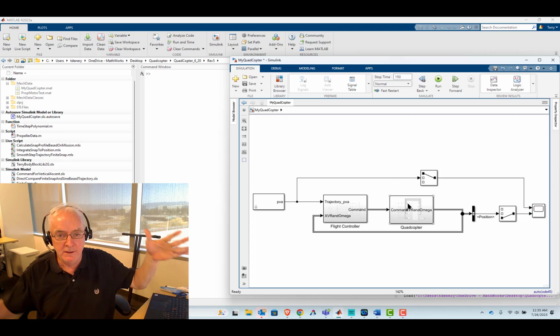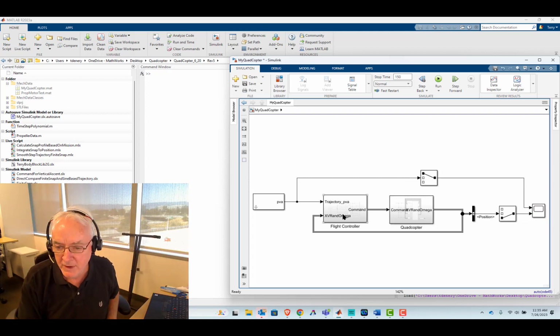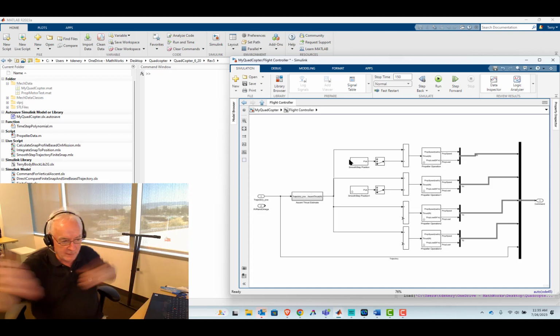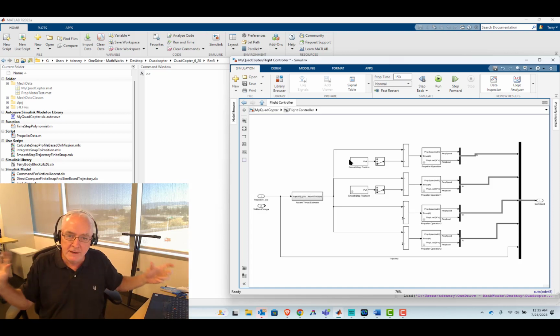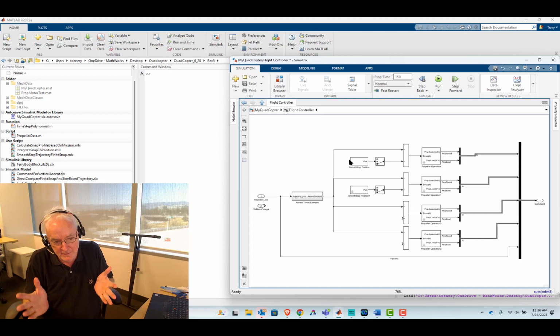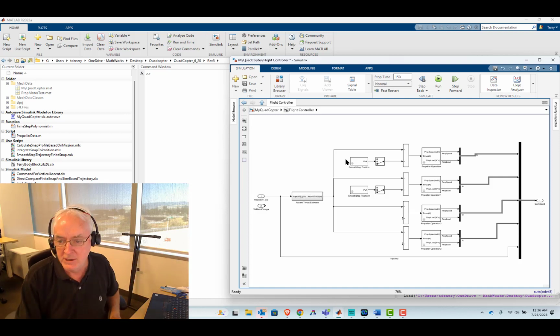I'll make the case that X and Y are pretty much the same idea, so I won't belabor that. But what I do want to do is the Z. And Z is a little trickier. In Z, again, I've got a quadcopter with my 4 propellers. It's this kind of rotation. All of that takes place because the propellers do have mass, they do have inertia, and as we torque off of those propellers, we're applying that same torque to the vehicle, right? And so we can do that in a coordinated way. We can achieve that Z rotation, right?